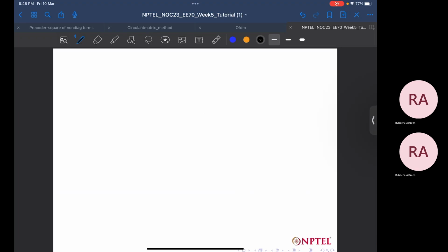Now that we have two different antennas, we have got multiple received signals. So now what will we do? We have to do some combining at the receiver to get the optimum received signal, right? So two categories of combining we will read here. The first one is selection combining, and the second one is maximal ratio combining.